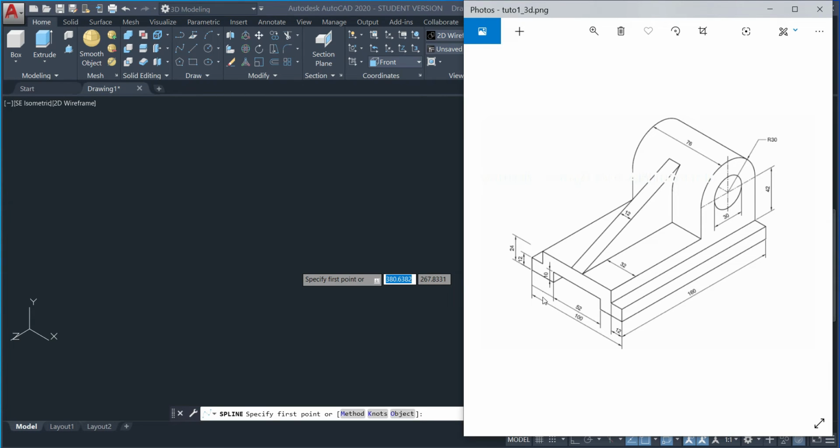Now as you can clearly see, the total distance from this point to this point is 100 and this much distance is 52, then the remaining dimension is 48, half on either side, therefore 24 and 24 on both sides. So 24, then we will move up 10 distance, then 52, then again 10 distance, then again 24.